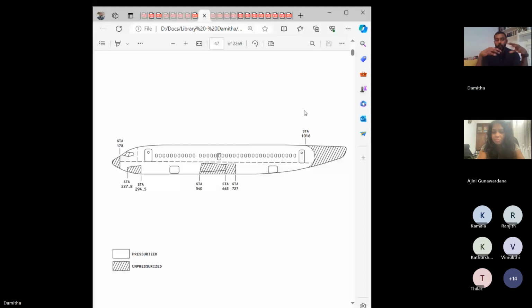So when designing an aircraft structure, or doing structural repairs or new designs, the structure should be able to withstand all these loads, not just once but over and over again. Over the whole life cycle of the aircraft, the primary structures shouldn't fail.